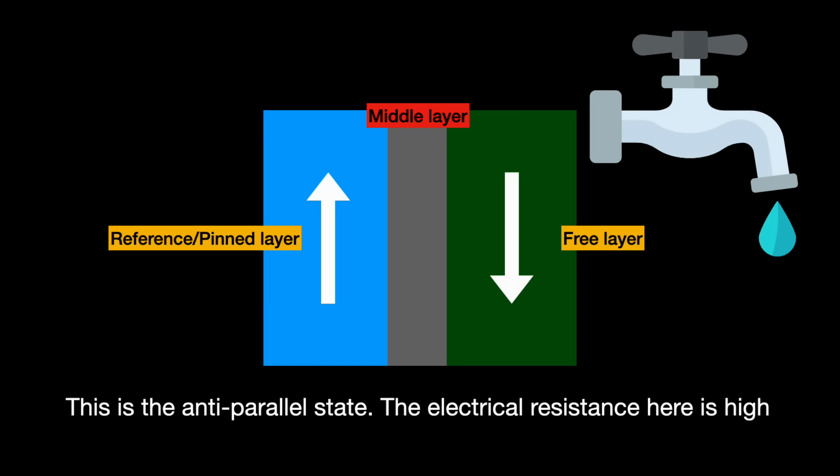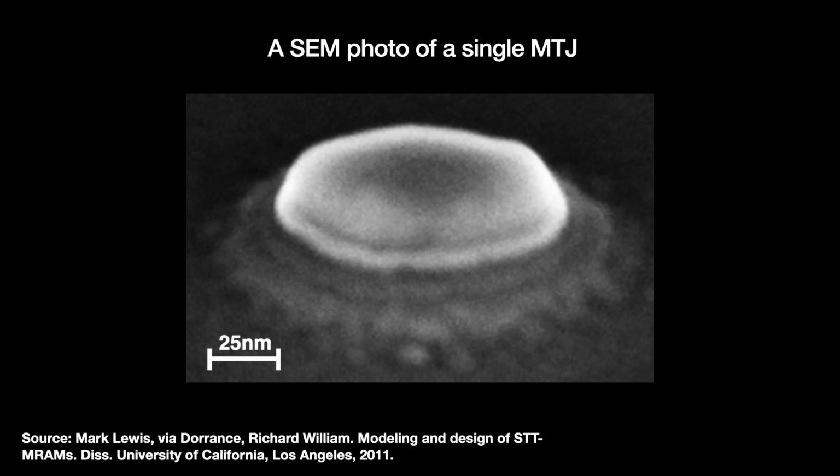We can map the two high or low resistance states to a bit. How is that done? With MRAMs, we send small currents into the MTJ to try and discern its resistance state, comparing it against a middle point reference level to determine the final value.